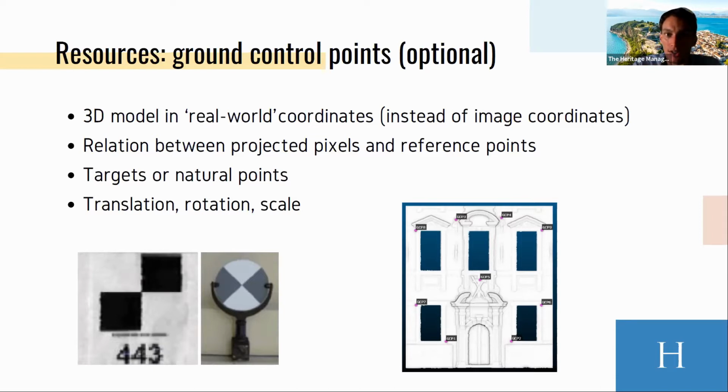Maybe, but I'm not quite sure, there is a metrical system in your 3D model based on the focal length of your photos. But even then, you can imagine that if you're working with a reference distance related to your focal length, so let's say that's 25 millimeters or 8 millimeters or 50 millimeters or even 100 millimeters, and you use that reference distance to model a statue or a facade or something else, in that case the errors, of course, will definitely diverge, and the geometric quality is very limited. Not the internal quality, but the absolute quality. So the quality that you will have if you do measurements on your 3D model.